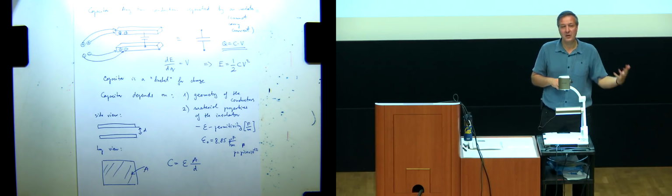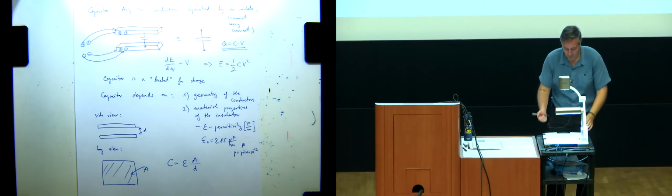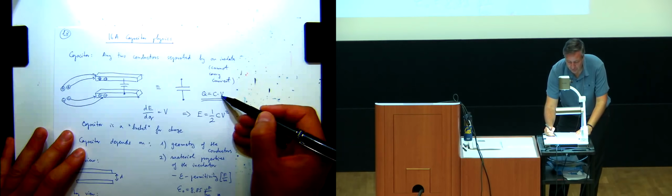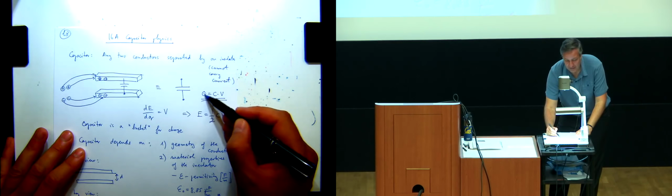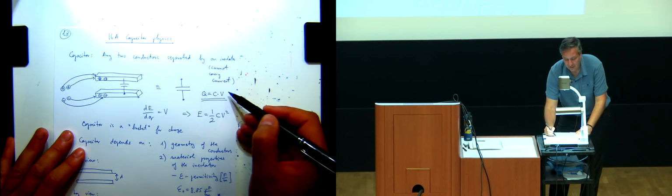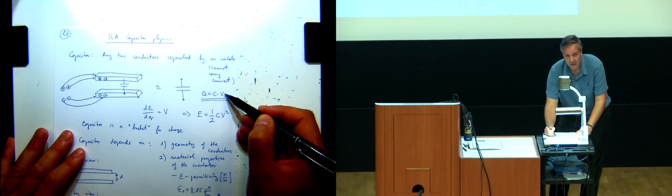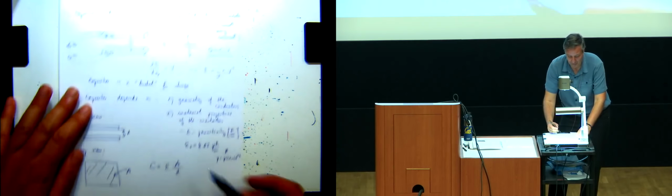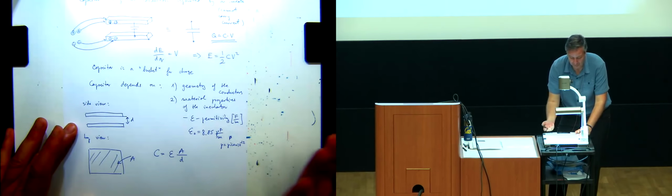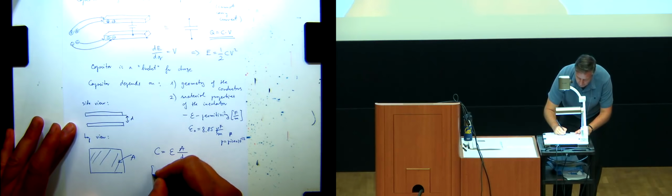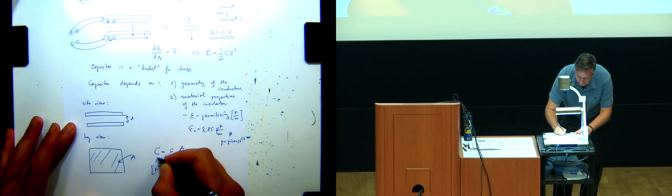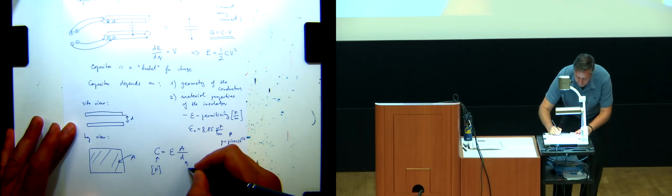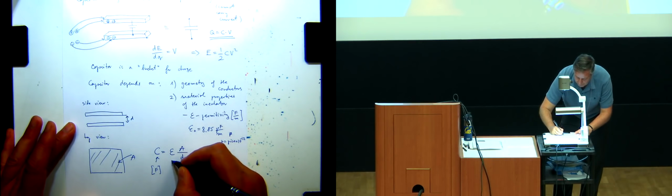And remember, effort equals voltage. So going back to this equation, if putting the same amount of charge gives me less voltage, then it's bigger capacitance. And so that's why if area is bigger, the capacitance is bigger. And so the units, again, are farad. For this, it is meter squared over meter. So the unit check for permittivity is farad over meter.